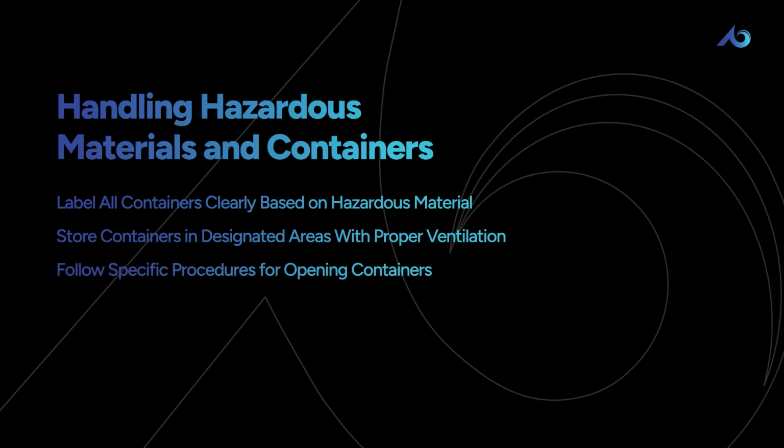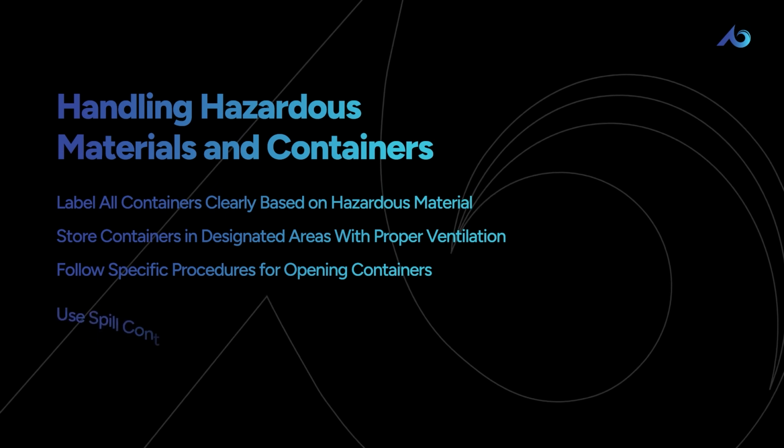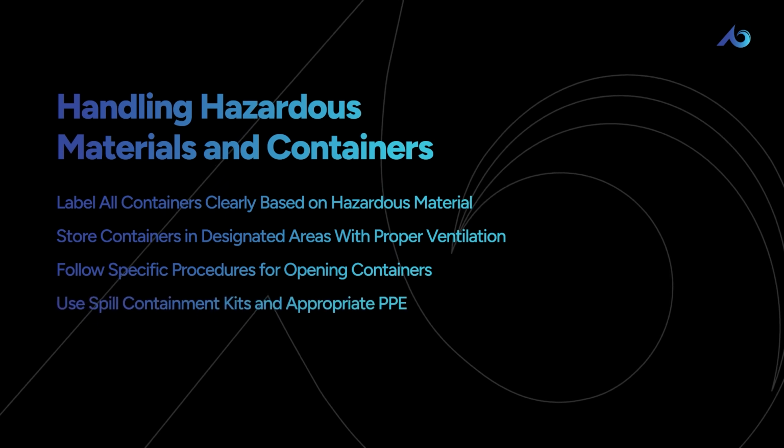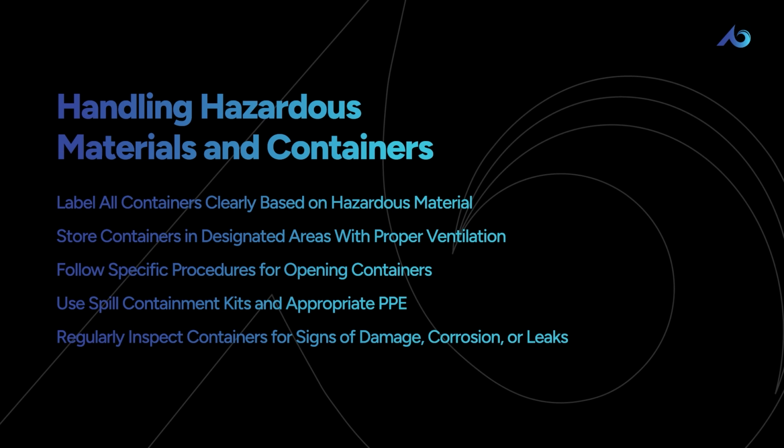Follow specific procedures for opening containers, especially those containing volatile substances. Be prepared with spill containment kits and appropriate PPE to handle any accidental releases safely. Regularly inspect containers for any signs of damage, corrosion, or leaks, and address any issues immediately.